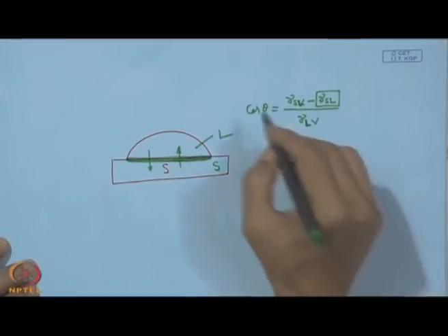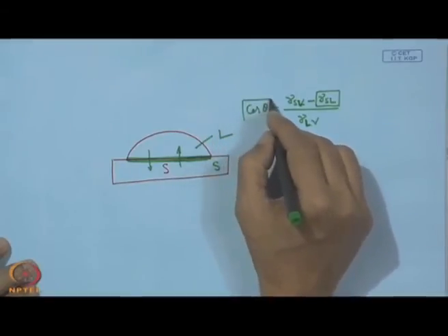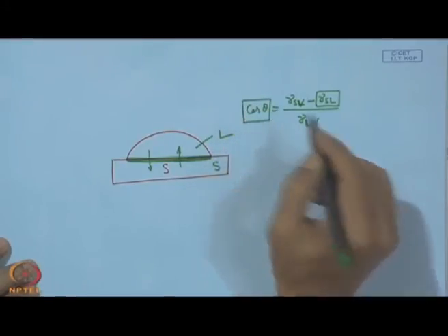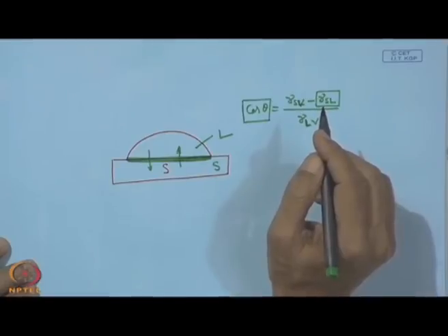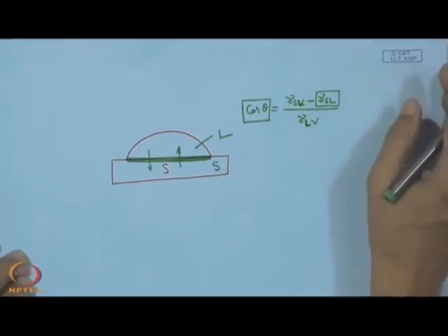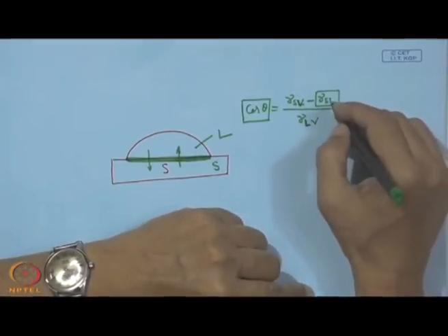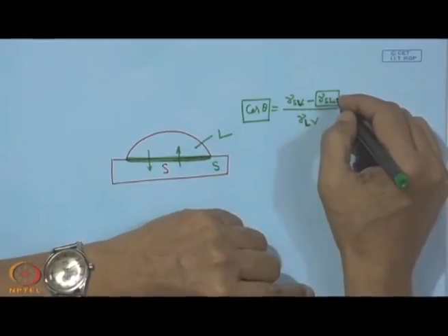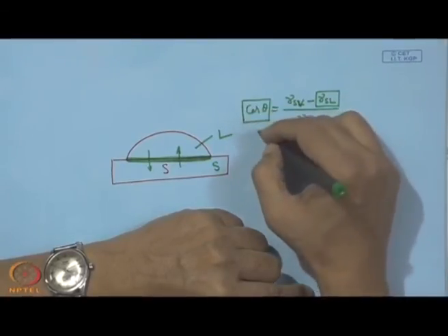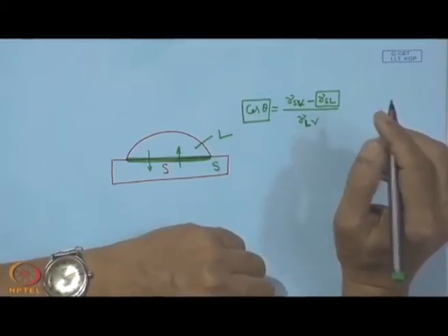That means the wetting angle is not just affected by van der Waals force of attraction, but the effect of diffusion, cross diffusion, reactivity or even alloying can have an overriding influence over the overall value of theta.